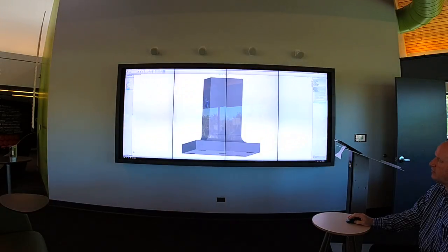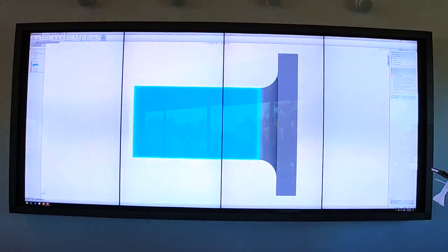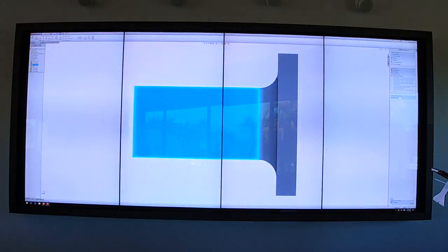You can add text, for instance. If I want to add text, I'm going to keep this here. We go to our sketch file, add text right here, and then basically you can add our text, which we can click into here. Now, again, you can change the fonts and things like that. You can change the size, you can make it bold. But once you've got your position in there, you can actually move it where you want it to be. And again, with smart dimensions, you're able to size that. Again, with that, we've created a text.